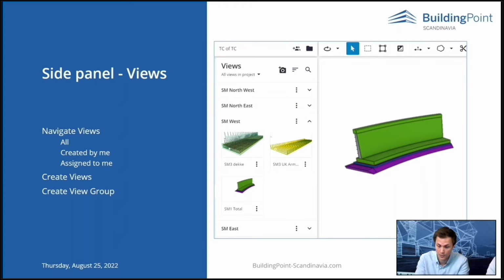So I didn't mention that earlier, but to-dos are also a way to break down the model. You can create to-dos as work packages, and in each to-do you will have your description, your documents, and related views. And when someone is performing a set of work on a part of the culvert, they will find the correct to-do, and everything is contained within there.